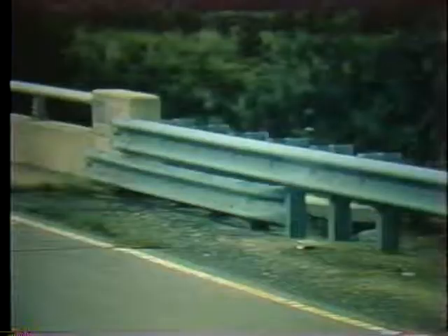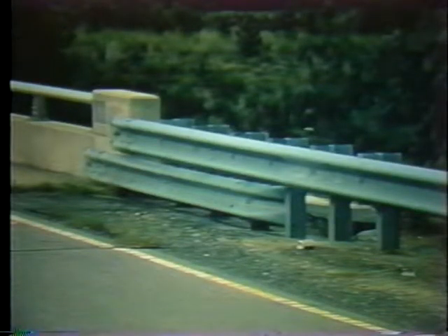We need to reduce the severity of accidents at transitions. One technique for reducing vehicle snagging at the rigid concrete bridge rail end can be seen in this next photo. A short section of W-beam is placed under the standard section to act as a rub rail. You can see that the rub rail is also anchored securely to the bridge rail face. The upstream end is tucked back under the approach rail beyond a post.